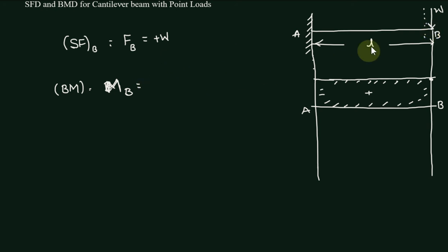So can you just remember what kind of bending moment sign convention it will be? It is hogging, right? Whatever load you apply on this cantilever, it will bend like this. This is hogging, it is bending like this, so you see it is crying. As per our trick in the previous video, that is negative bending moment. Hogging, negative bending moment, so a cantilever carries negative bending moment. The bending moment at B is 0. Yes, we have the load, but the distance is 0 because the load itself is acting at B. There is no distance up to B, right?